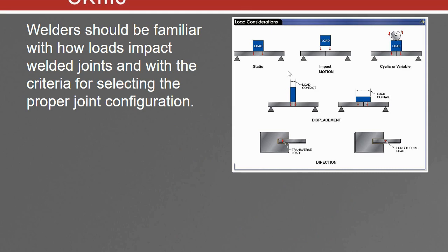If we have our load in the center here, and let's say, for example, this is 2 inches wide, we're going to have all of our pressure on a 2-inch wide piece. Chances are we're probably going to bend that. Now if we go over here and say this is 6 inches wide, so now instead of our surface area covering 2 inches, we're now covering 6 inches here, and we're going to have more load displacement, so that means we're going to have less chance of this actually bending here.